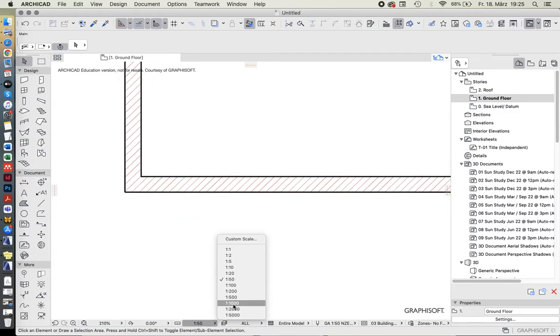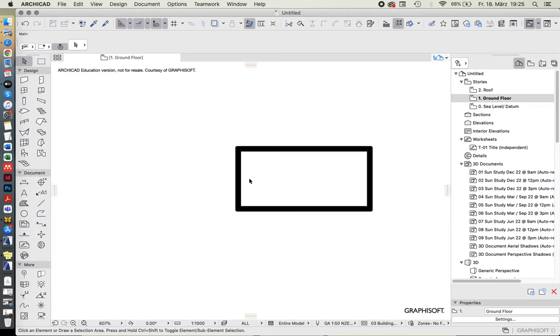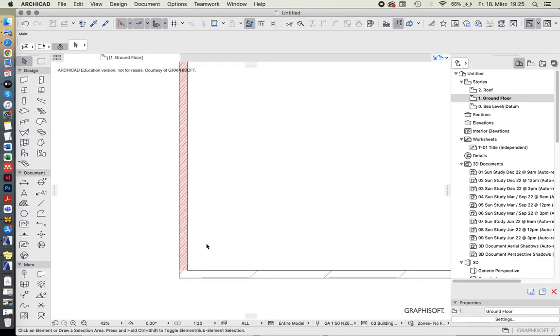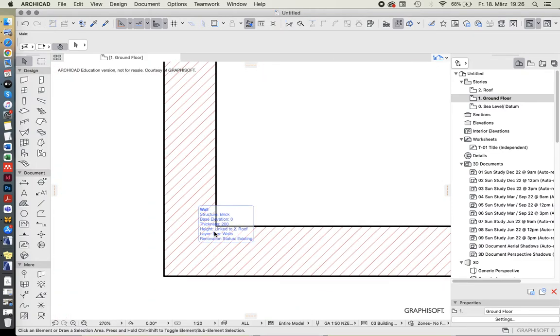If you do zoom in and we are changing that scale, our hatchings and line width and everything will change accordingly. So whenever you are drawing something, make sure that you're drawing it at the right scale, because as you can see, these line weights are different. The hatching has a different line weight, as does the cut line, and these are adaptive to the specific scales. That's something that you should learn how to do. It's a standard within architectural orthographic representation, so it's very important to pay attention to these sorts of things.